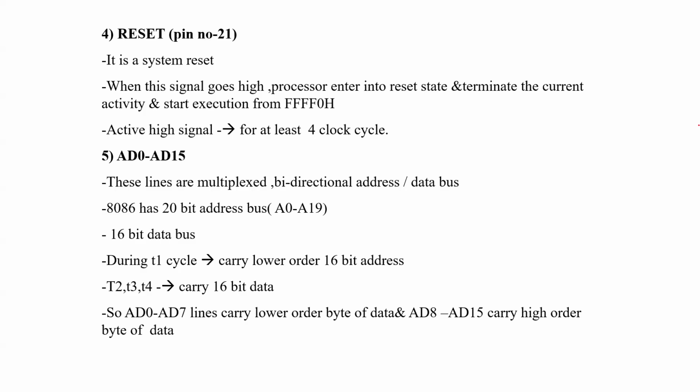It is a system reset pin. When this signal goes high, the processor enters the reset state, terminates the current operation or activity, and starts execution from FFFF0H.